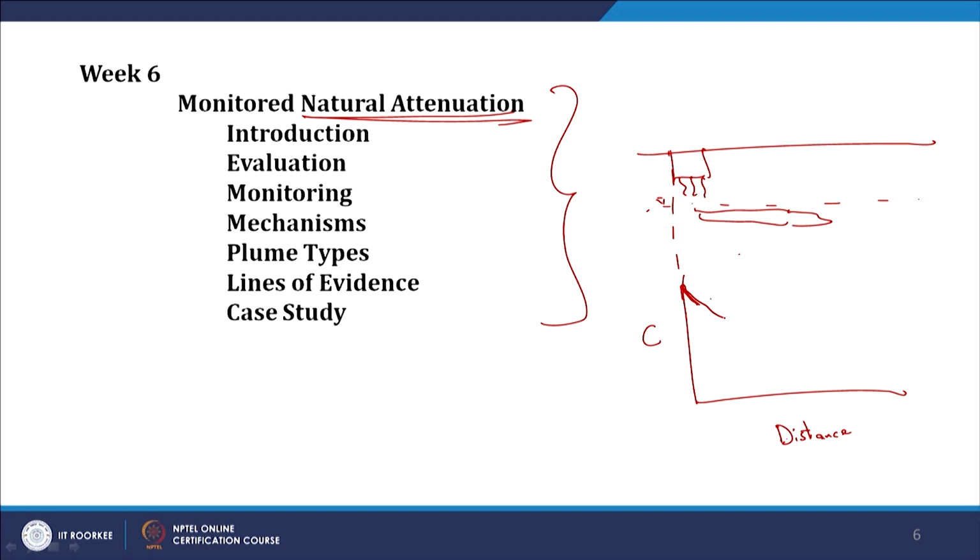Let us say I can construct a PRB here. If I construct a permeable reactive barrier here and design it in such a way that at the end of this particular, it is not to scale, pardon me, by the time it reaches the PRB there is going to be a considerable drop, and then I can let the microbes do the job. Here we have the extraction wells where people are drawing the groundwater from. By the time it reaches this particular point, we are going to design it in such a way, in conjunction with both the PRB